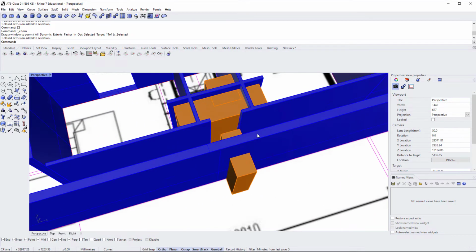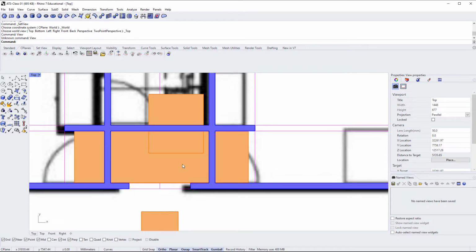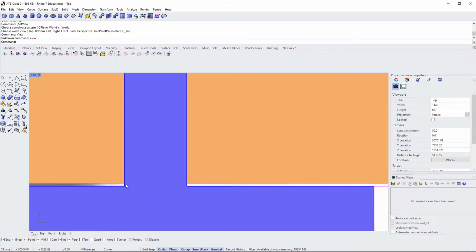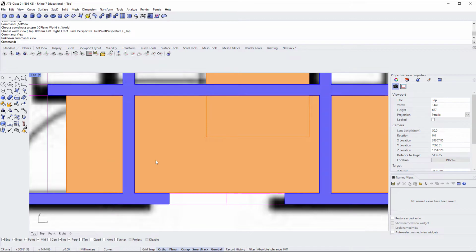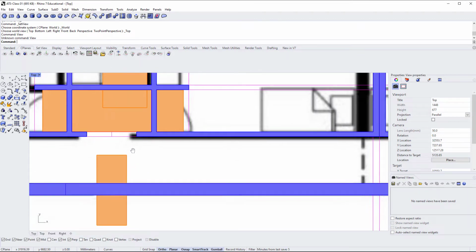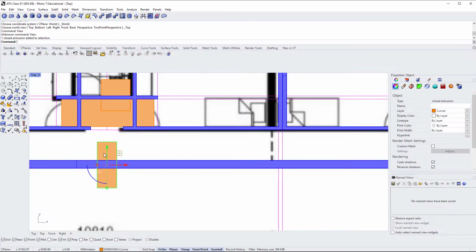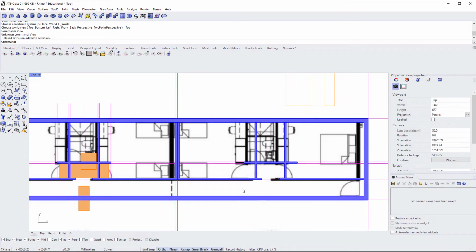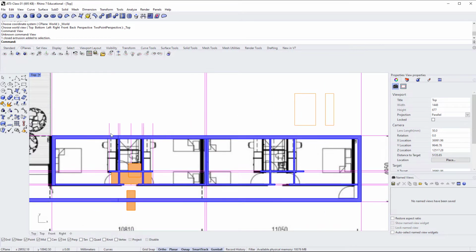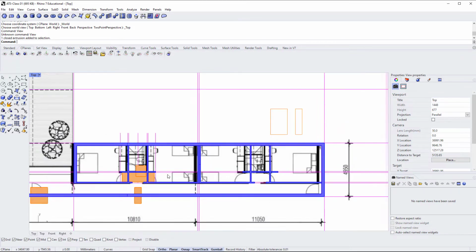In the bedrooms as well, everything is relatively rationalized. The important thing is that there is a tiny gap between the two sides of the walls and the doors. It's very tight, but it will do. And these hallway windows are actually to the center line of the bathroom. If I was doing this as a project and just sketching out, windows will be somewhere around here, doors somewhere around here, there needs to be some sort of common principle around it, especially considering that these are modularized compartments that are brought to site. You want to rationalize them so the same design principle can be copied across.